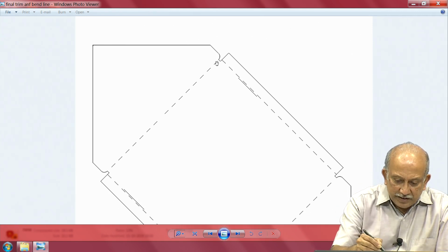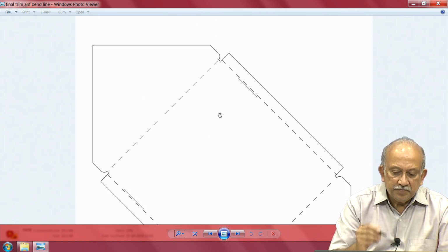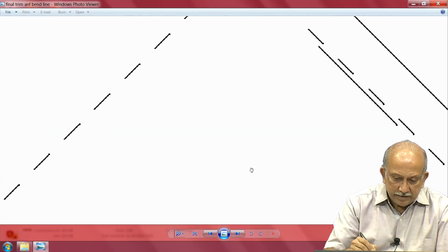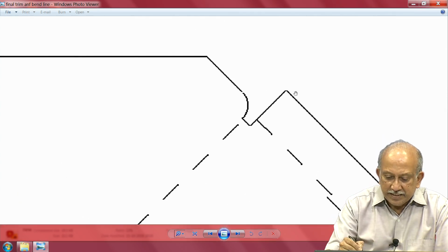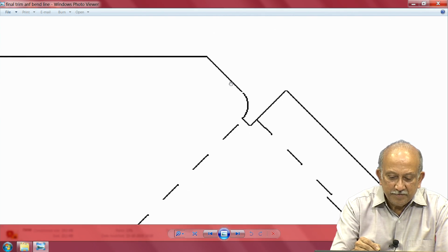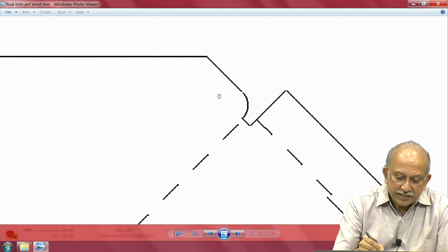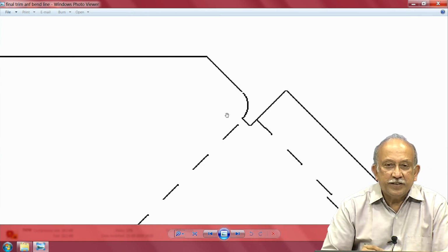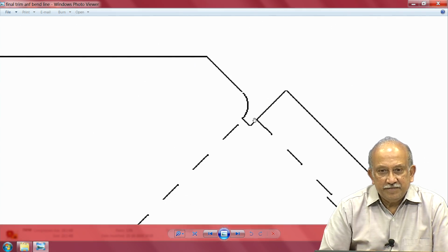And when we come into this corner, we end up with a very nice arrangement. Something has to go inside, this limb has to go inside this thickness. See this limb, which depending on the sheet has to go into the thickness, so that limb will come here, and there is already this circular portion, it has to go inside. To accommodate this, one thickness relief has to be given.